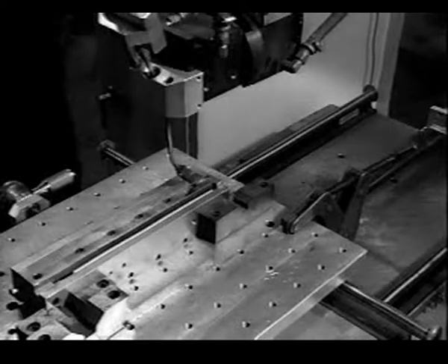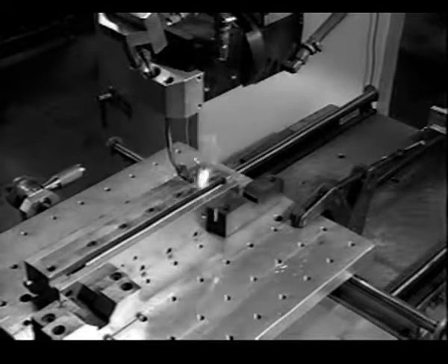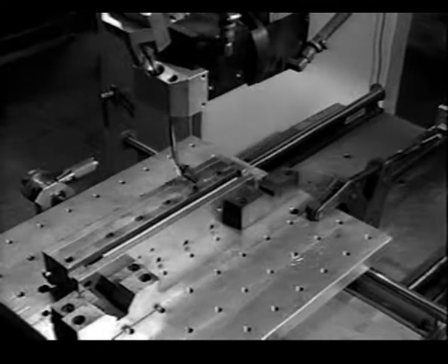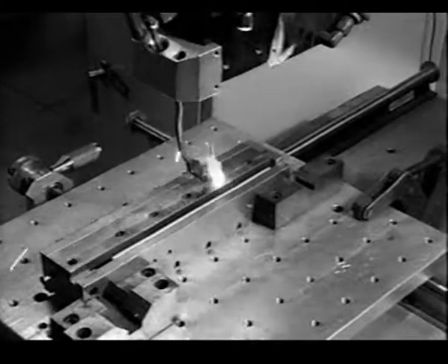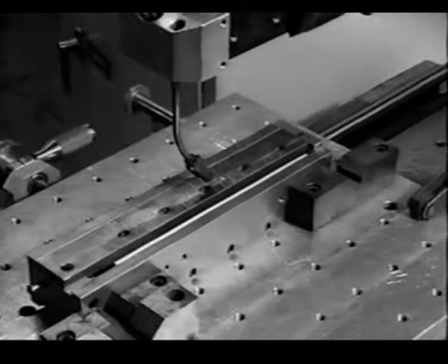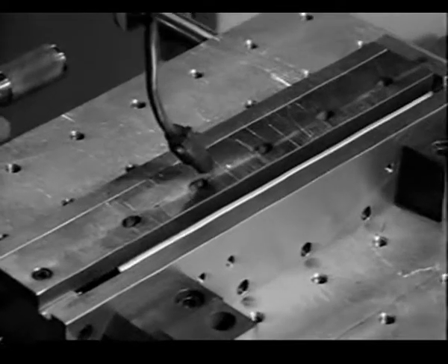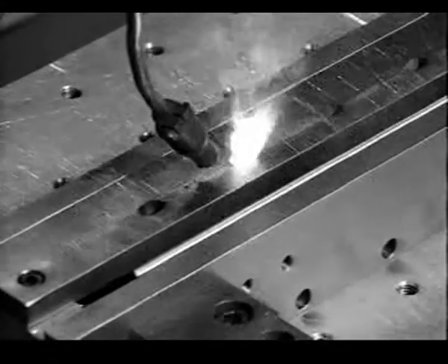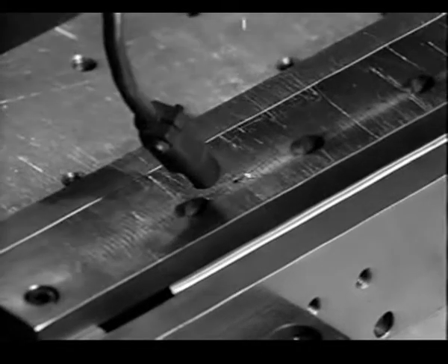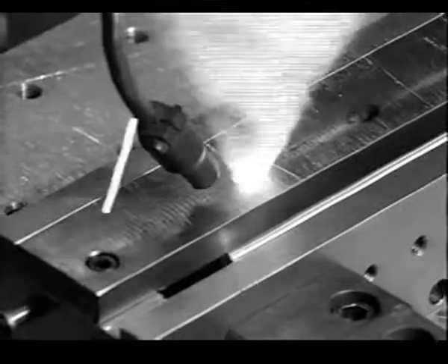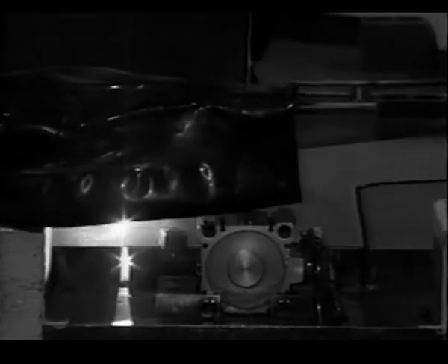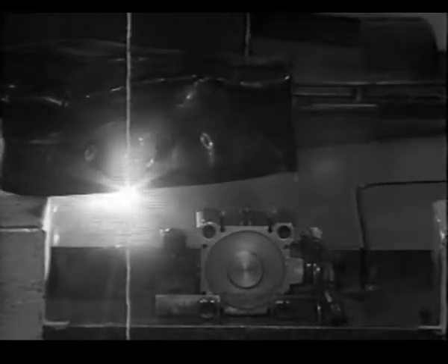Welding speeds are usually much higher than other welding processes, thus limiting heat-affected zone size and workpiece distortion. In addition, because of the intense, precisely focused heat, welds can be quite deep. Also, welds can be made in confined regions and between dissimilar metals. Laser beam welding systems are used in many industries and are typically fully automated and computer controlled.